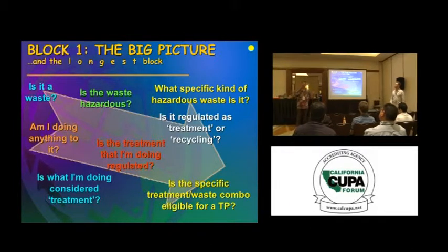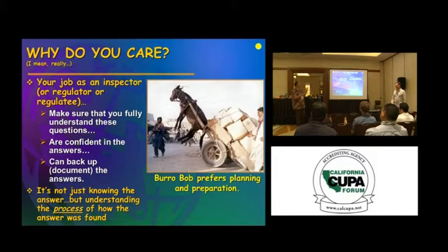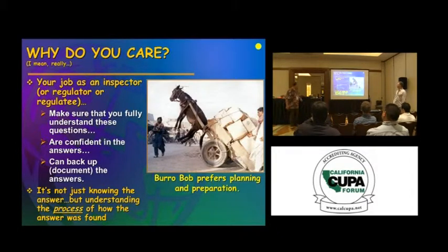No. Is the waste going in there hazardous? Well, it's only 0.5% oil. Run a fish kill, it doesn't kill fish. Run the metals, it's fine. It's not a hazardous waste. You're not treating a hazardous waste. You're removing a hazardous waste. So you really need to go through it step by step before you get to the other stuff. So why do you care?